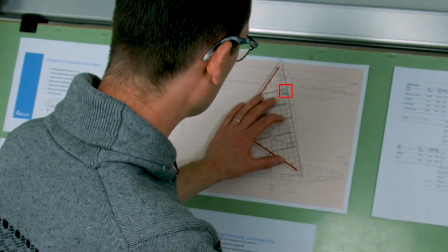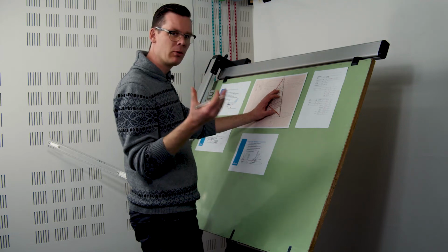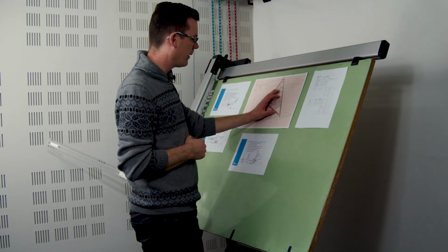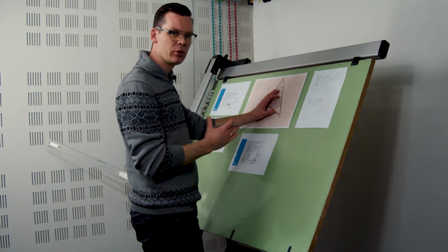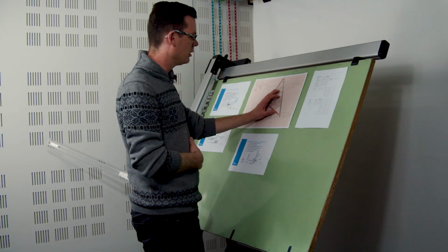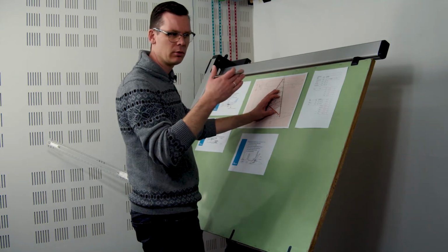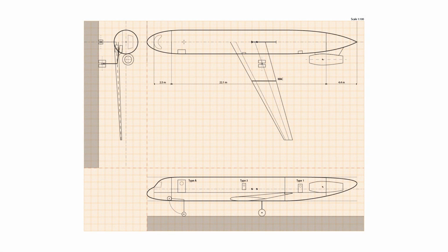I would say I would put the spar a little bit more forward, just to make sure that we can mount the strut behind the aft spar and actually use the inboard part of the aft spar as the bulkhead of the fuel tank. Right, so let me just notionally shift it a little bit aft. It gives me a little bit more space for flaps as well.